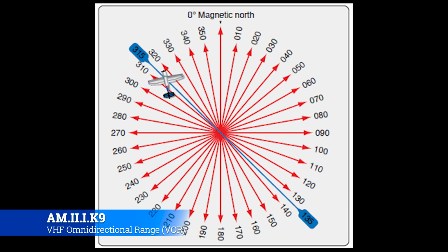So, VOR produces a signal that transmits and propagates 360 degrees from the unit and is used by the aircraft to navigate to and from the station with the help of an onboard VOR receiver and display instruments. A pilot is not required to fly a pattern to intersect the signal from a VOR station, since it propagates out in every direction.